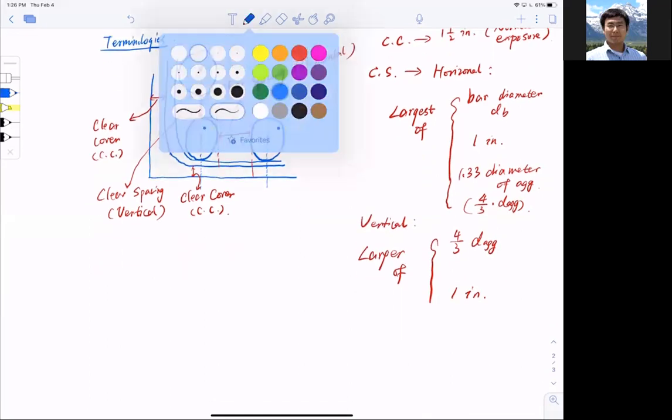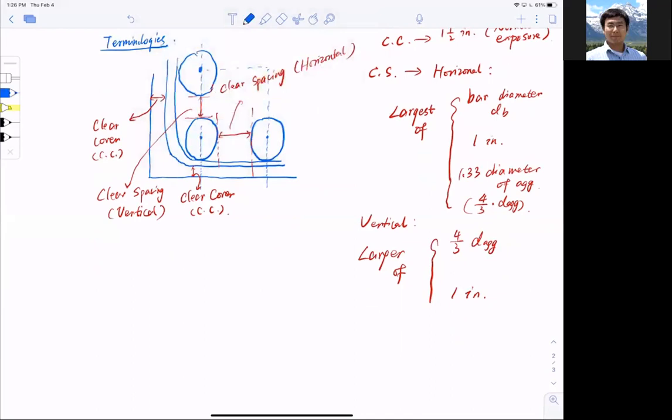If I want to put bars in, for example, if I want to put 5 bars in a section, I take a look at the section and say, you know what, I'm going to put 5 bars in. So first thing, I need to put 3 bars, because it's 5. I want to put the higher number of bars in the bottom row here.